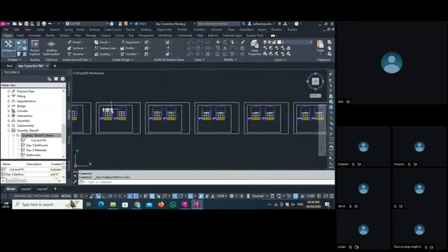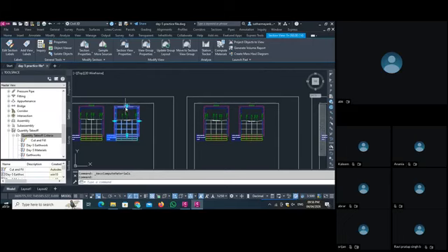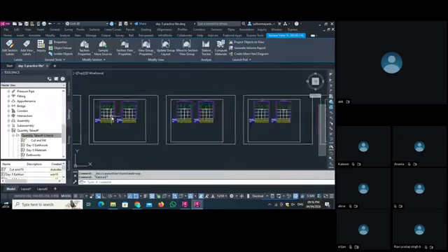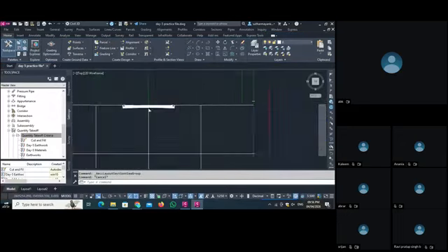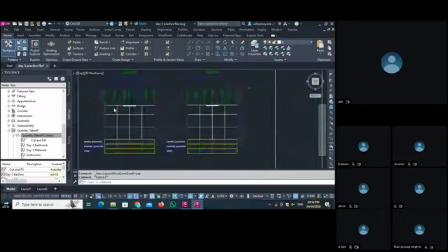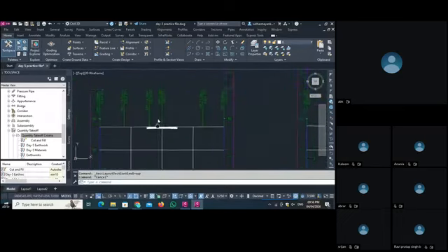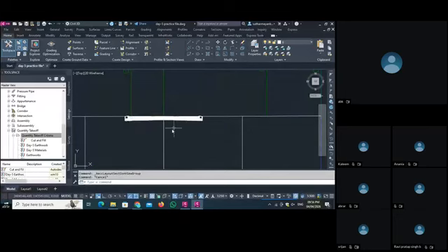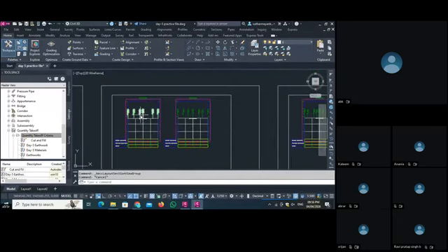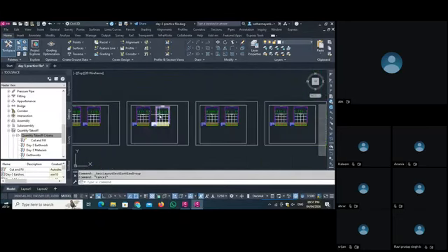Even if you want to make sure that everything has come through, what you do is select one cross section and update your group layout. As you update your group layout, it will update automatically in all profiles. See, this is our change number 40, and we set it here. So now, again go to the analyze tab.